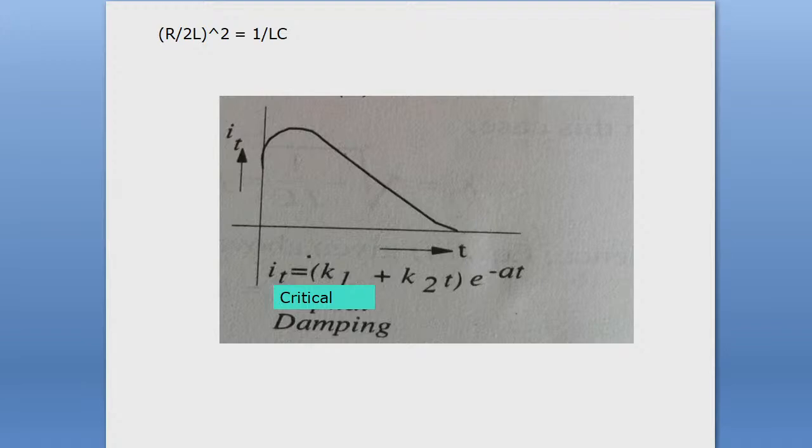You see the response part, the transient response part. If you notice, for the overdamped case there is a cosh term or exponential term present, and it takes a long time to reach zero value. But for critically damped, the response has two parts, one exponential and another a linear part, the t term. Due to the presence of the t term, it initially increases. After getting a maximum value, it then decreases. So that's why you get such a curve: initially increases, then maximum, then decreases.